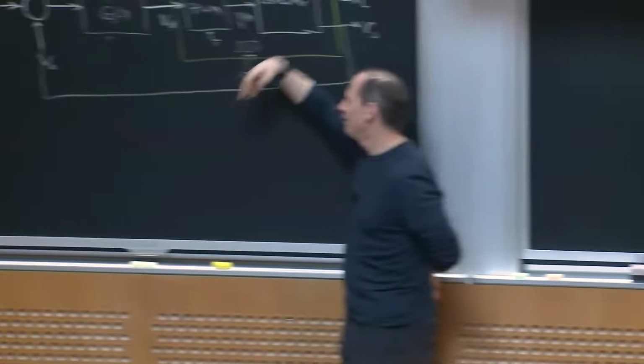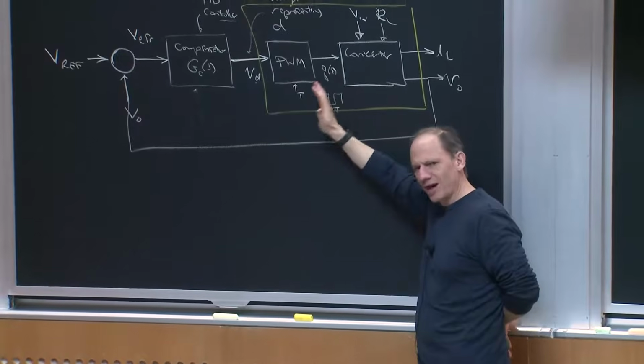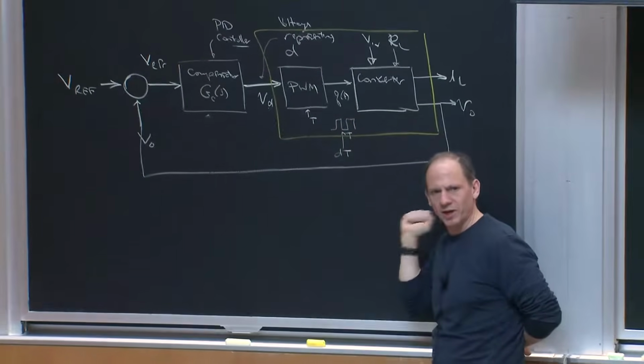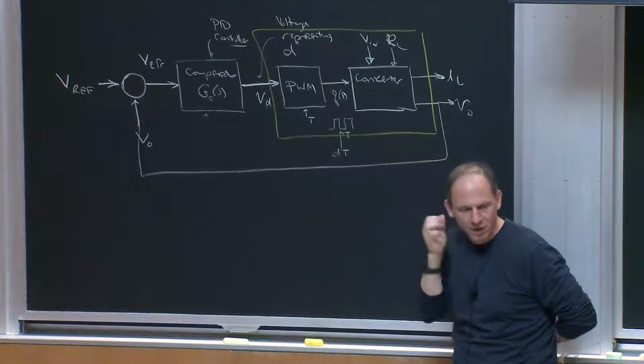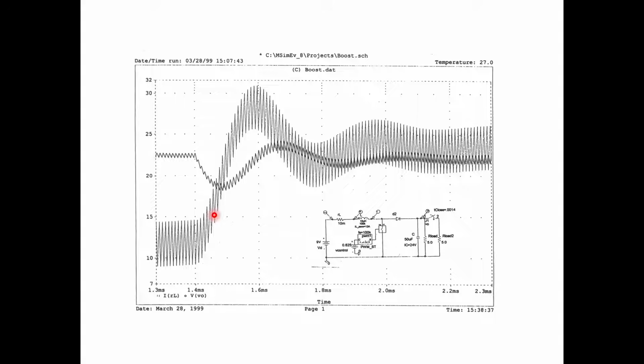My whole notion was that at least within a cycle, duty ratio is not something that I'm swinging around wildly, right? So I'm interested in the behavior of this circuit for frequencies relatively low compared to the switching frequency, okay? So what I want to do is generate models that capture this average behavior, like these low frequency oscillations, and ignore the switching ripple. Okay, everybody follow that?